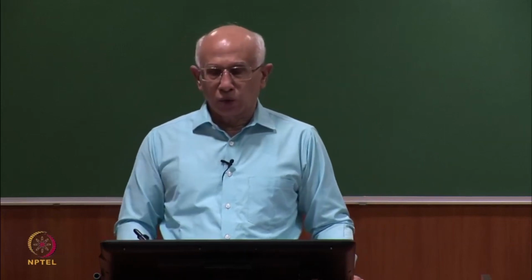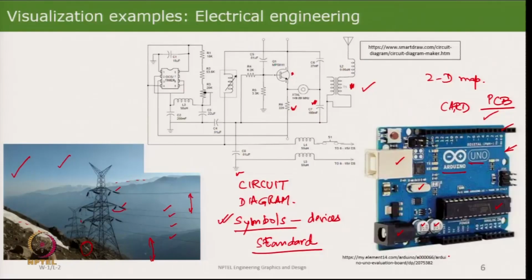Designing the layout also involves looking at not just the electrical requirement, but also the physical requirements. For example, these two devices have to be separated by a certain distance. Although their electrical connections could be much closer, physically the two devices should be somewhat away. This particular chip sitting on the top here has a certain dimension, and you have to keep other things away from it.